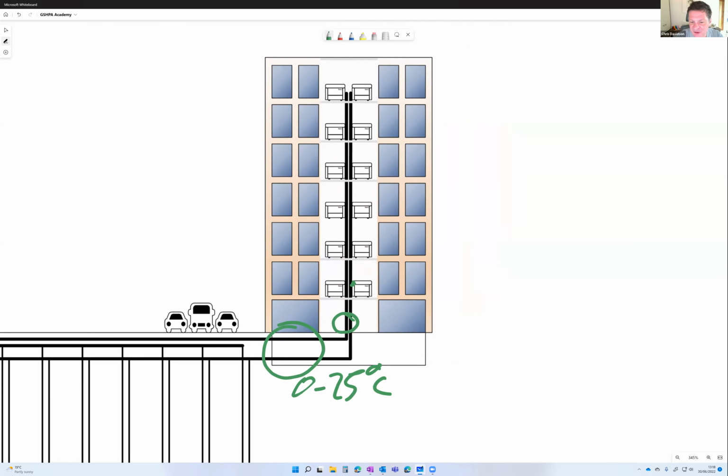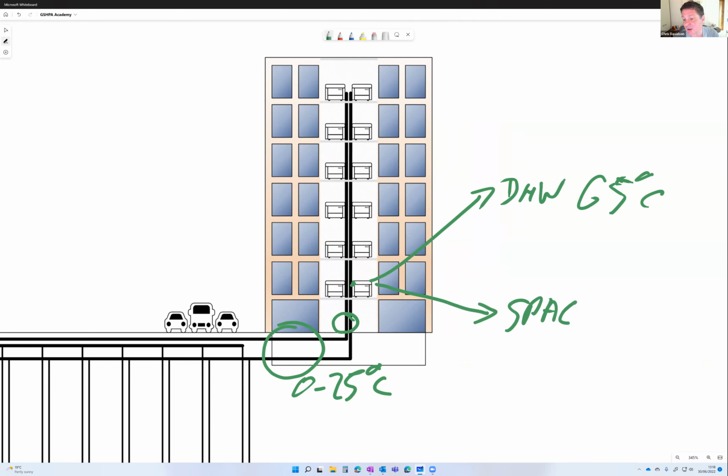Second thing is, we can actually get this heat pump to do domestic hot water when it is required at the temperature at which it is required. So say 65 degrees, to keep it consistent with my previous example. It can then turn off that domestic hot water and go down to the space heating temperature at, say, 35 degrees, again, to keep it consistent. So we're only actually going up to that higher temperature, which is a lower efficiency regime for a heat pump, when we have to. So that is a very important point to make, that we're only doing one or the other. We are taking full advantage of that low temperature space heating by only doing that or the domestic hot water, but never both together. So it's a very, very different engineering proposition.